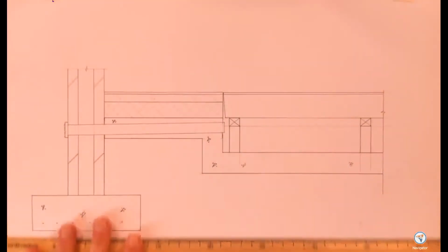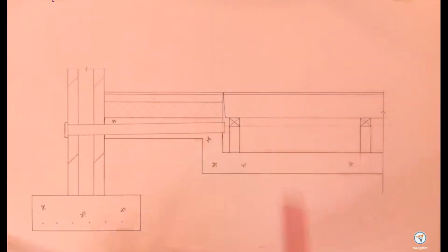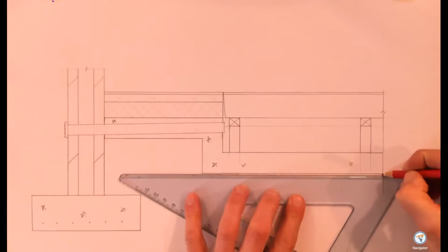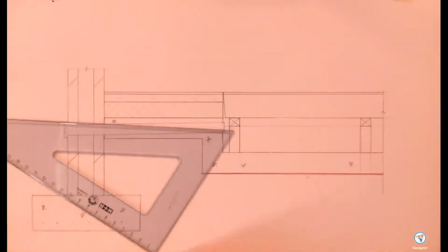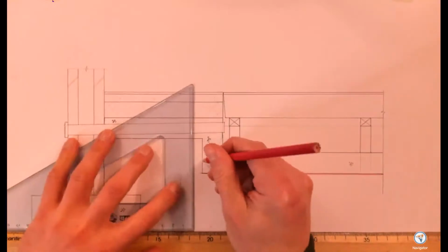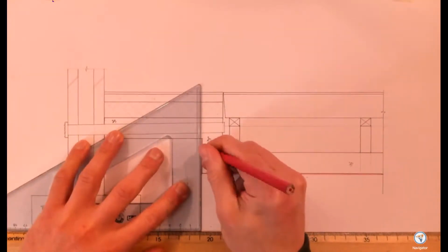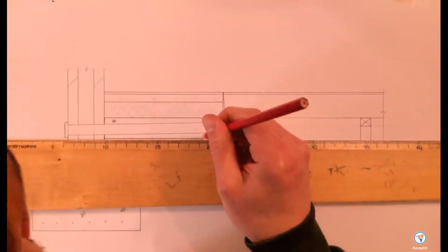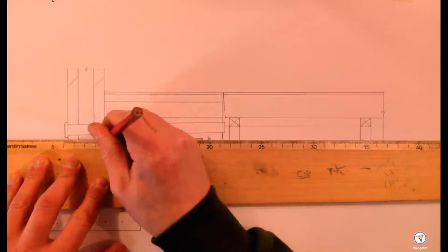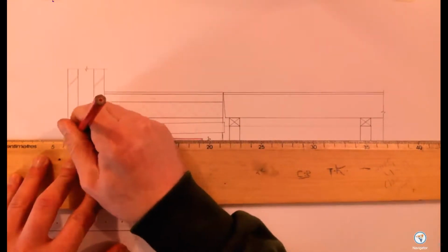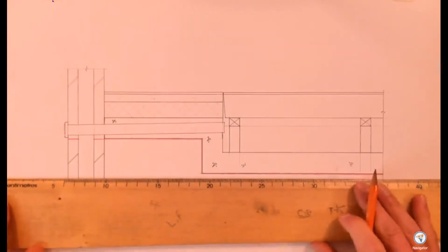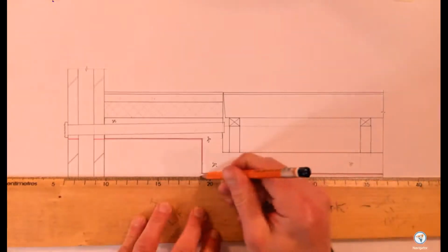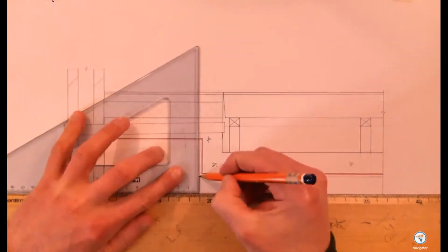We need to put in a damp-proof membrane. It could be put above the subfloor, but for this drawing we're going to put it underneath the subfloor. It just makes it a little bit easier to draw. So it comes along and it is going to continue under the entire subfloor, and right out through the wall. Okay, so that is the damp-proof membrane put in, and then it'll turn to damp-proof course when it goes out through the wall. We need to cushion that to stop it getting punctured, so we'll put in a thin layer of sand underneath it. So sand blinding under here.